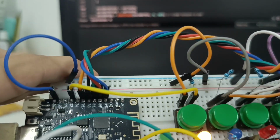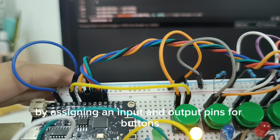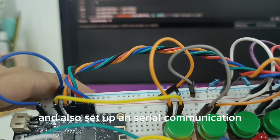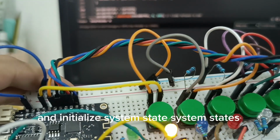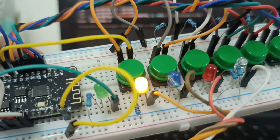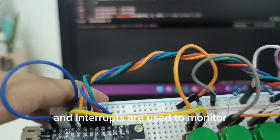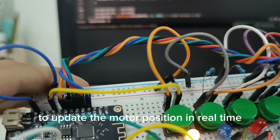of the motor. First of all, the program begins by assigning input and output pins for buttons, LEDs and encoder channels. It also sets up serial communication and initializes system states. Interrupts are used to monitor changes from the encoder to update the motor position in real time.